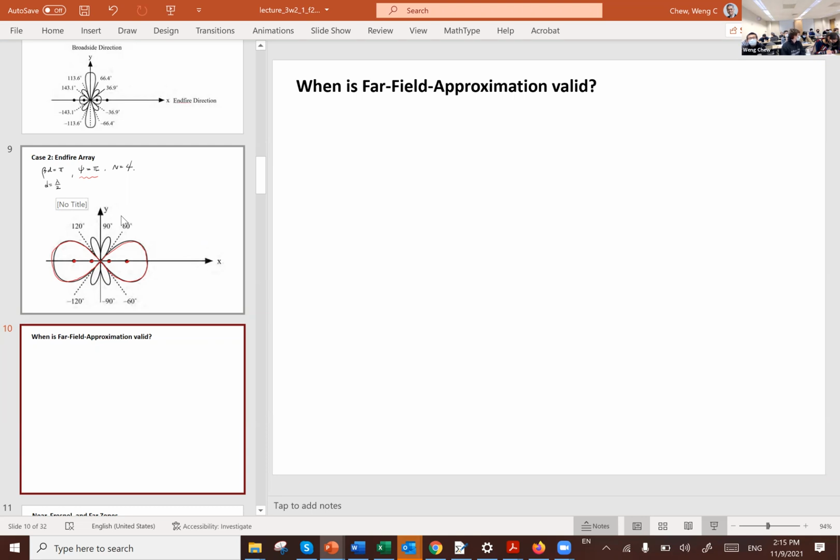There, you see by changing the phase, you get a symmetry. So by changing those phases, you get to rotate these radiation patterns. So you can have this kind of phased array system, which is a very important technology.